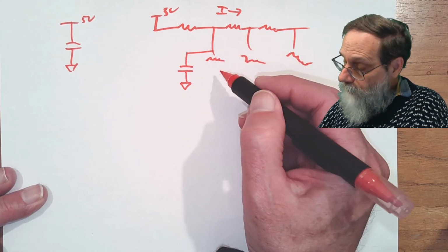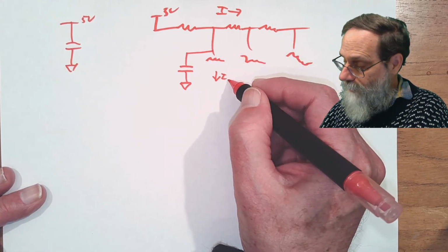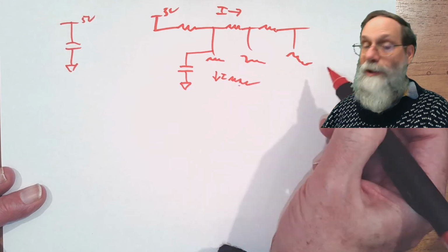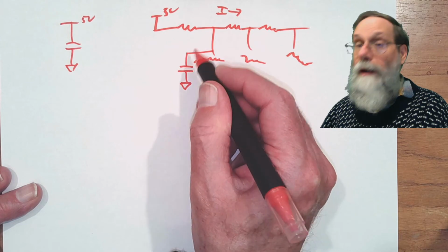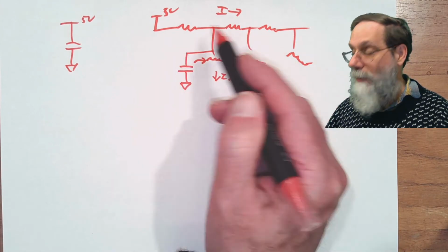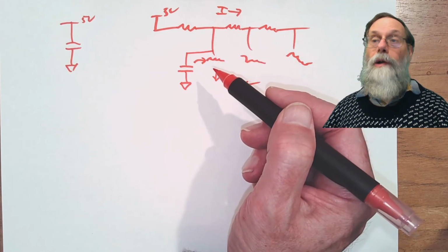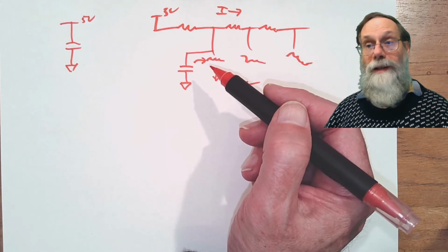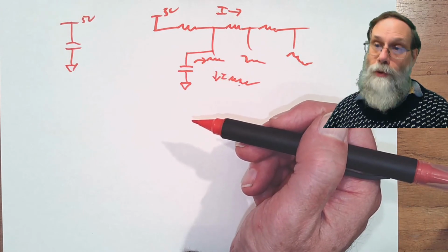Another thing is that if the fluctuating current is coming from one of these chips, so this is where you've got that fluctuating current, well, that fluctuating current can come from charging and discharging the capacitor rather than coming from the power supply, and so you're reducing the amount of noise you're injecting into the power supply node. So the bypass capacitors do two things.